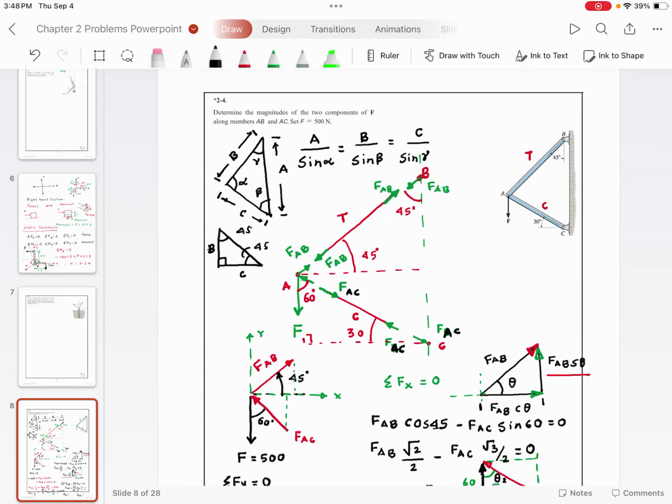In other words, I want you to look at this force triad. Why is it called a triad? Because three forces. You can only use this trick when you have three forces. If you have two forces, four forces, five forces, six forces, you cannot use this trick. If you have a force triad and all these three forces are passing through the same point, then you can construct something called the force triangle.